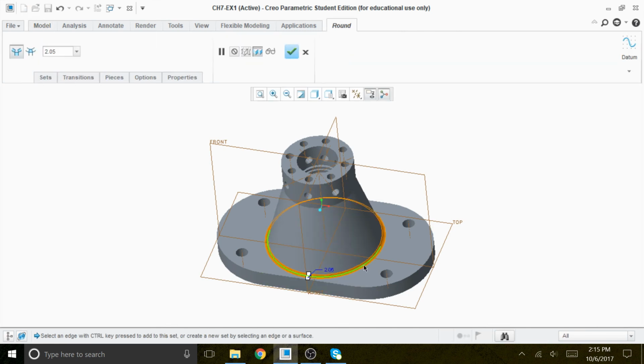For stiffness, for the strength of the material, in order to increase the fatigue life of this kind of part, if it's subjected to cyclic loading, it's a good idea to create a fillet radius or round that will improve the fatigue life of a part, because upon impact, if it's not reinforced by a fillet radius, it is going to snap, it is going to break. So it's a good idea for the design to add a fillet radius on that circumference on the bottom where this tower merges with this surface here.